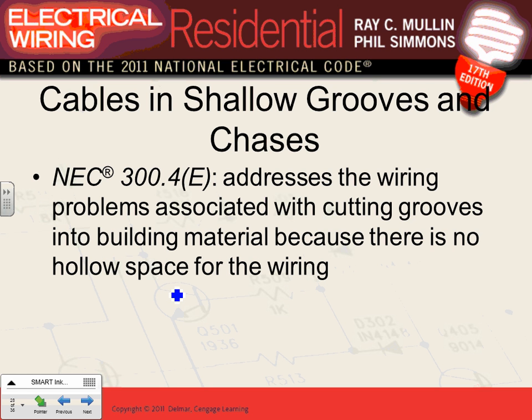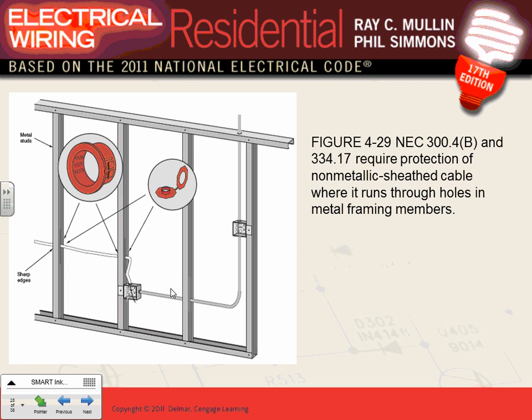So it talks about cutting grooves. You can cut grooves in the wood, as long as you again maintain that 1/16 protection. If you're using metallic studs, Jeff, as you've probably done tons of them, you have to use protectors to protect the conductors. What do you guys use? You use MC cable and what?